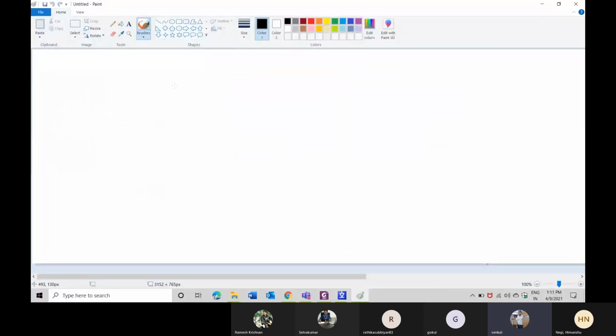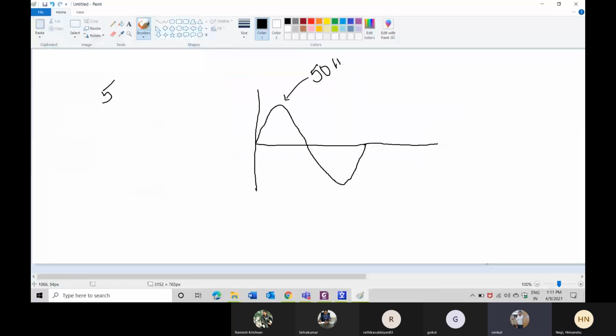To be more specific, here we have created 5 types of fault. Now what we have done is take a particular scenario in a sine waveform. Just assume this is 0.3 and this is 0.32. This is a single waveform for a 50 Hz system, which is 20 milliseconds. In that we have differentiated the value from 0.3 to 0.31 as different instances, with an increment of 0.001.